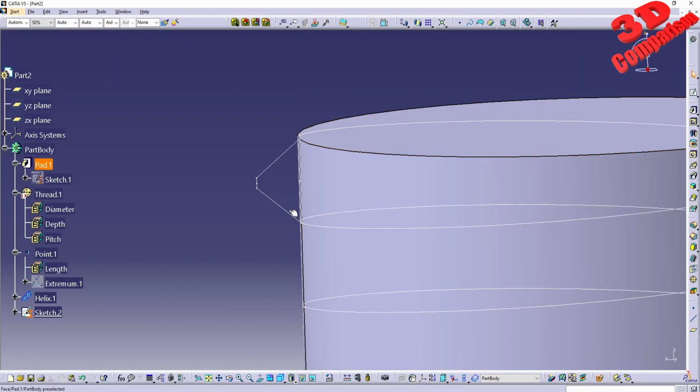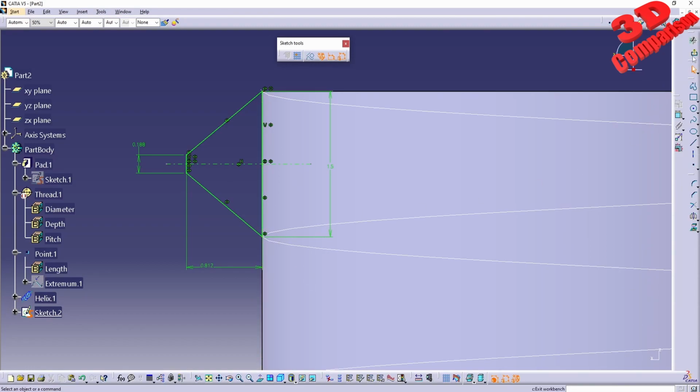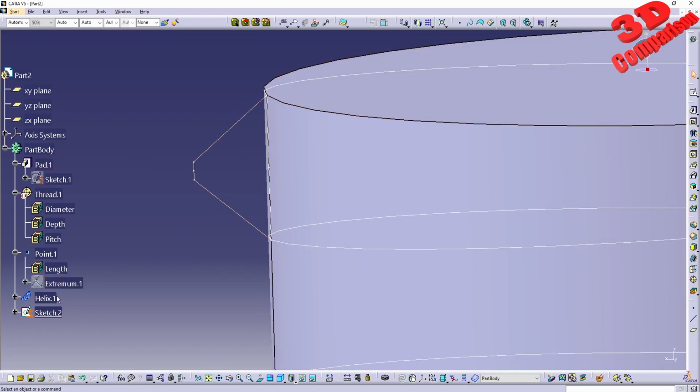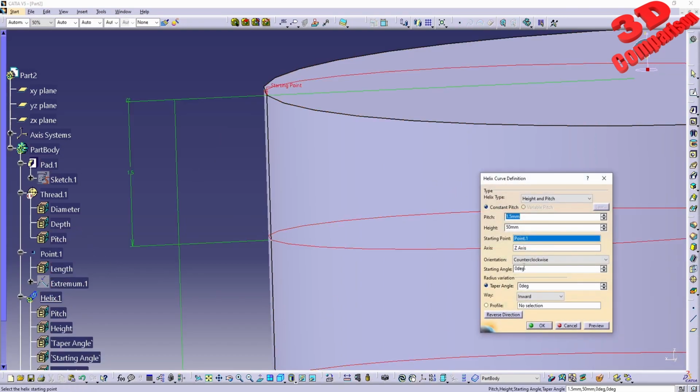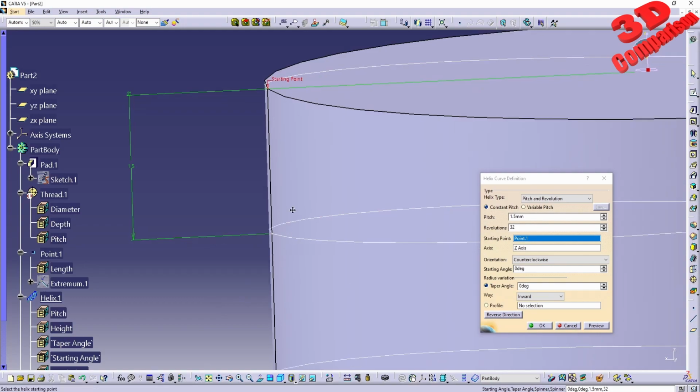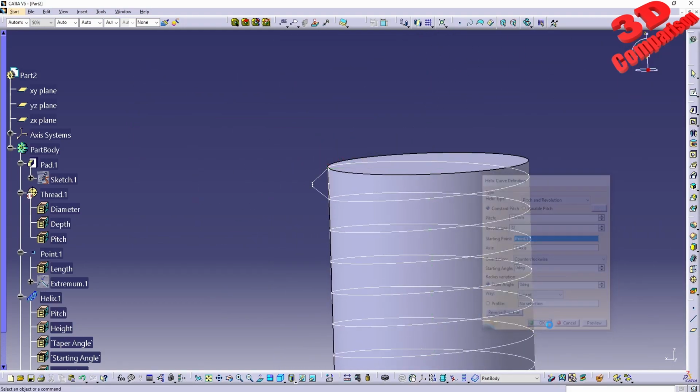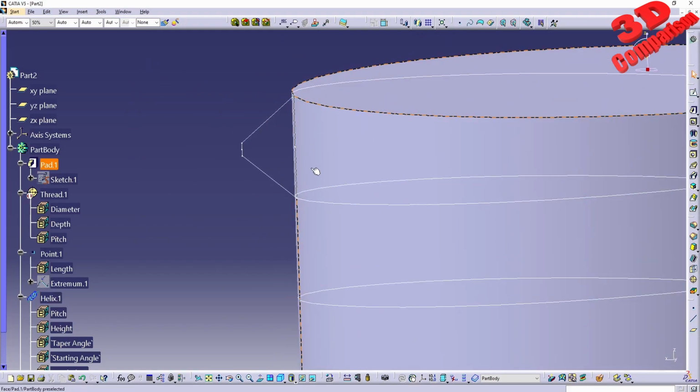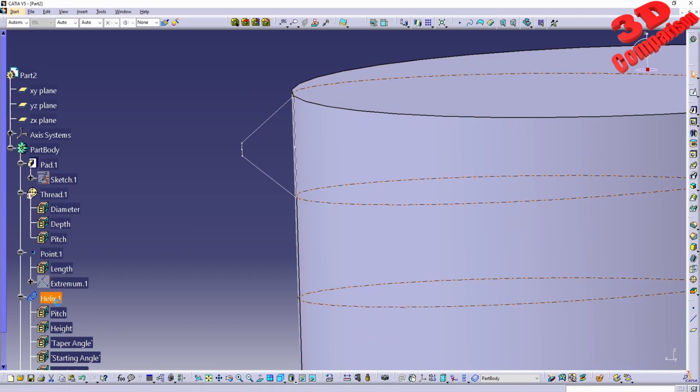Let's just quickly change this within the sketch. So let me define the new rib. I will change the helix a little bit in order to be similar to that, which worked. So I'm just going to add 32 revolutions for this. It should be the same pitch because the values are the same.